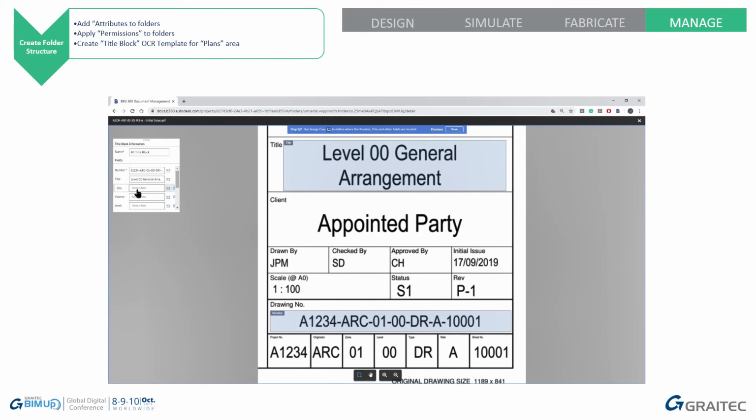And then I've separated all of the different containers into separate areas in the title block. That's so that OCR can read it easier. It won't pick up any hyphens, or if you've got ones instead of zeros where they'll squish up, it just means it's a much easier way of reading that title block information. We can save lots of time in our project doing this.